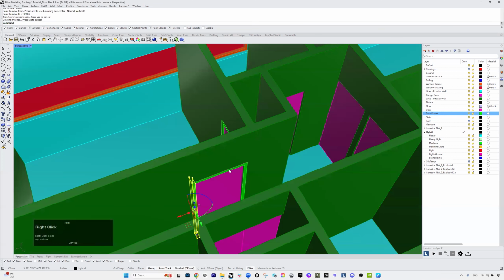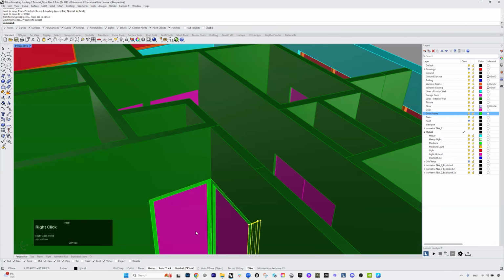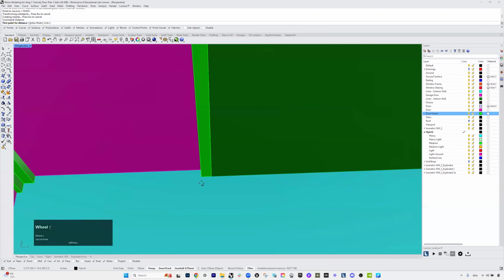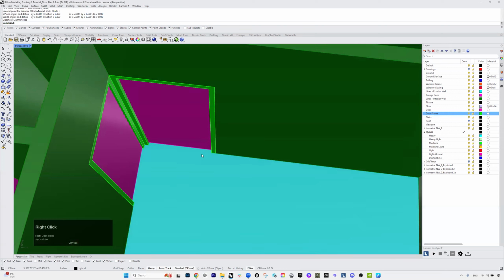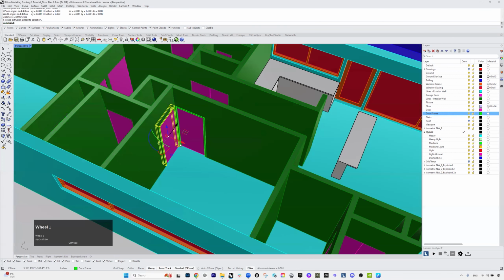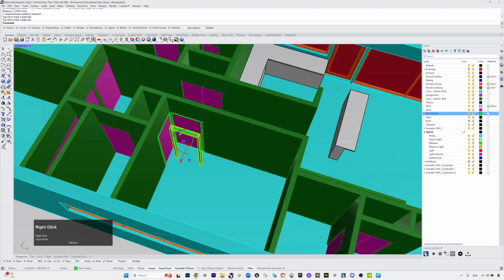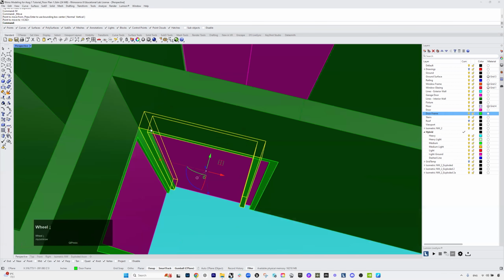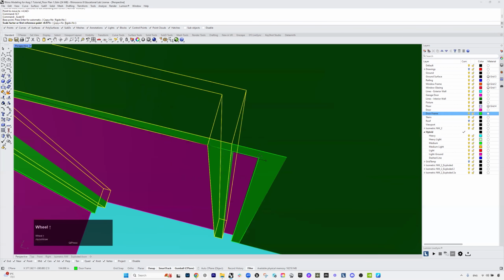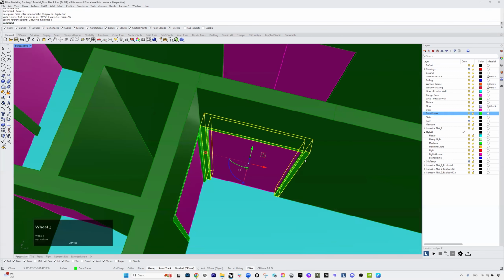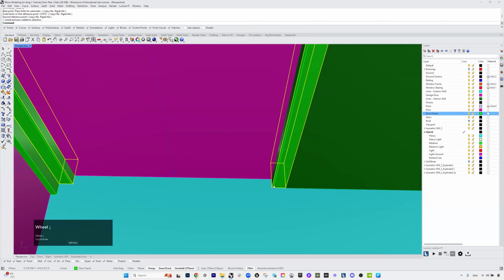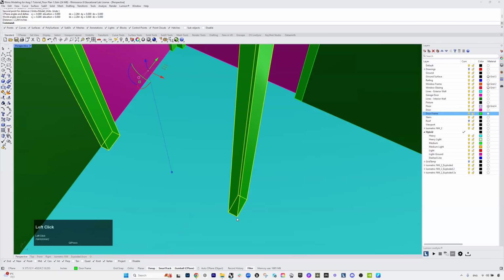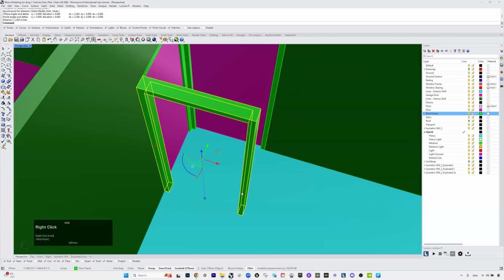to stretch the door frame geometry. And in this case, the distance of the door frame over here will remain 2 inches. If I try to do this with scale 1D, for example, that will be different. So scale 1D from here to there. Then you can kind of see in here, the distance from here to that point is 2.264 inches, which is not what we want.